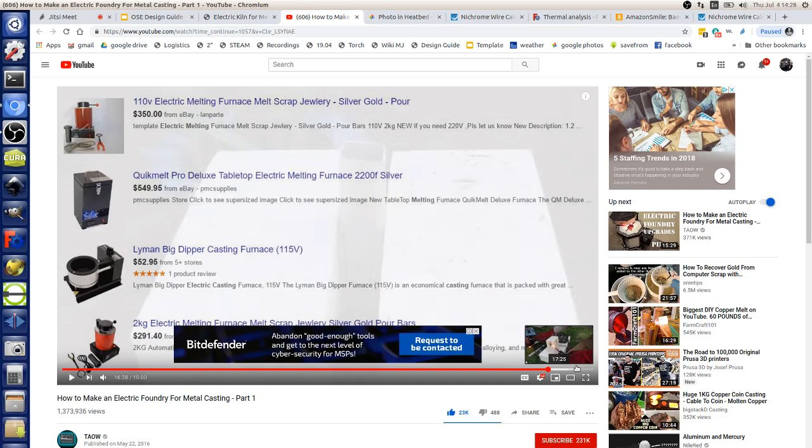They also have special filament where you can 3D print the object, put the cast around it, and you can pour directly into it and it burns out. There's some specialized filaments that you can use to do exactly that. So this becomes a method where you can convert your 3D prints to full metal objects in aluminum at least.